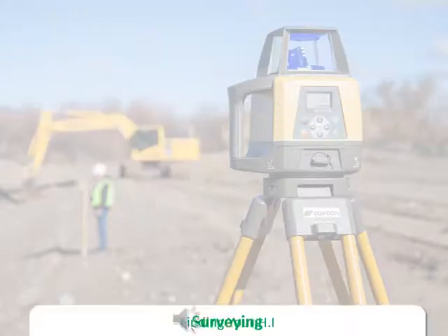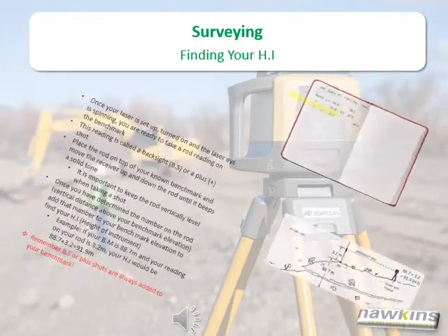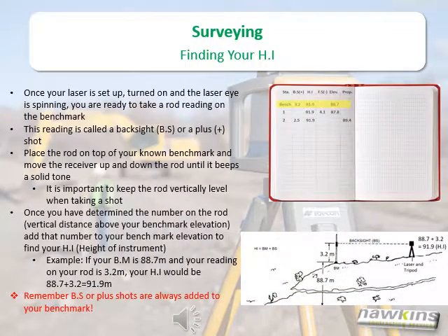Finding your HI, or height of instrument. Once your laser is set up, turned on, and the laser eye is spinning, you are ready to take a rod reading on the benchmark. This is called a backsight or plus shot. Place the rod on top of your known benchmark and move the receiver up and down until it beeps a solid tone. It is important to keep the rod vertically level when taking a shot.